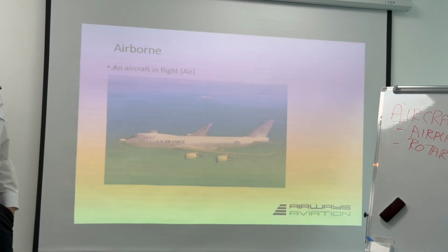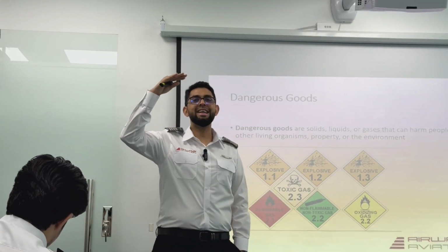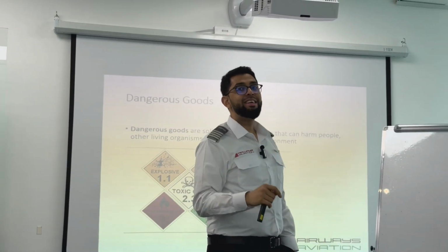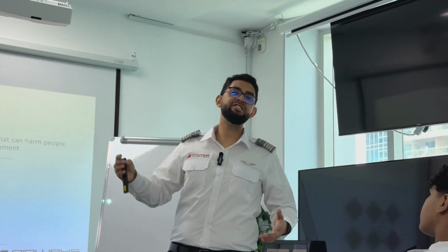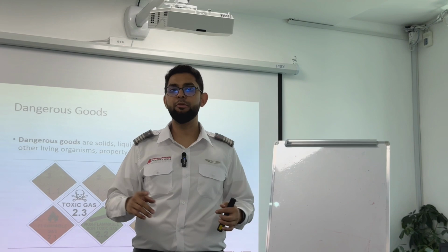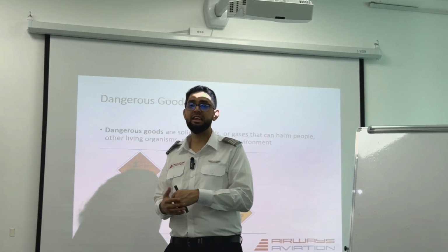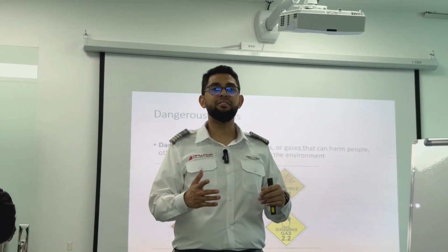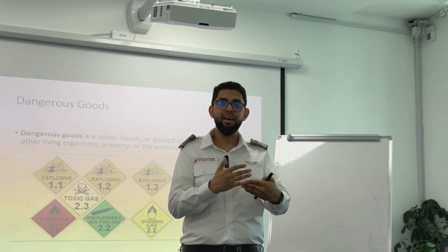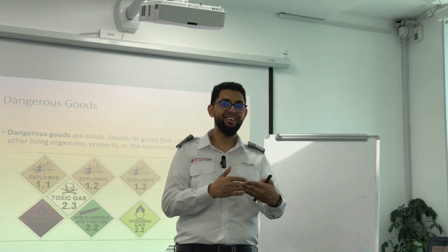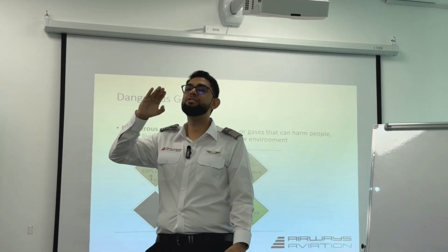Now, the word airborne, maybe the picture is not... No matter what kind of problem you have, if you had a certain amount of altitude, you would definitely be able to solve the problem, no matter what the situation is. Engine shut down, 40,000 feet, no worries, I've got enough time to try to restart the engine, try to figure out what's the problem, turn on the fuel pumps, maybe it's a fuel starvation, maybe it's a vapor lock. I have enough time to figure it out, restart. I even have time to pull out a real physical book and try to understand what might have gone wrong with the engine. I have enough time to do anything and everything because I'm at a high altitude. So altitude is always your best friend.